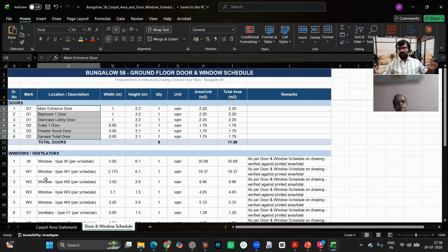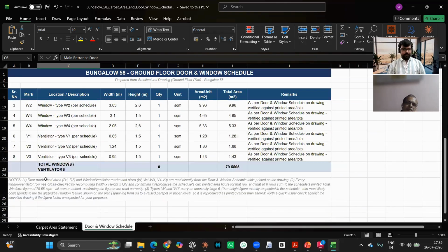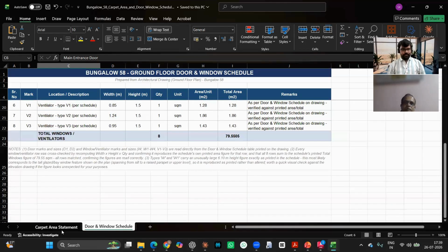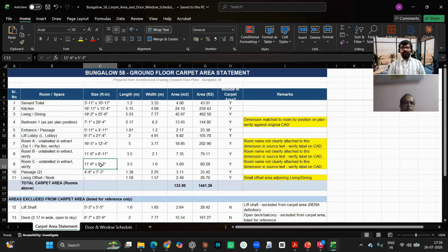If all your drawings are ready from architecture, structural, plumbing, then we can calculate on the basis of drawing and specification, and we can create two kinds of submissions. One is a measurement sheet, one is an abstract sheet, and then we can create a complete BOQ within that particular submission format. Okay, so this is great. So it's a good journey.